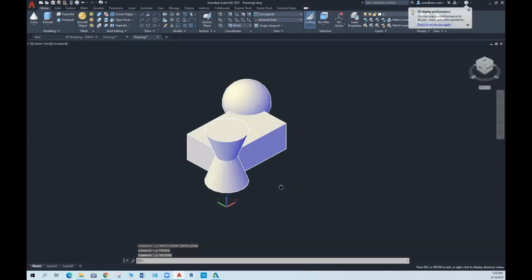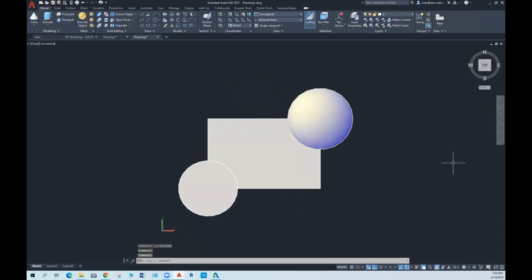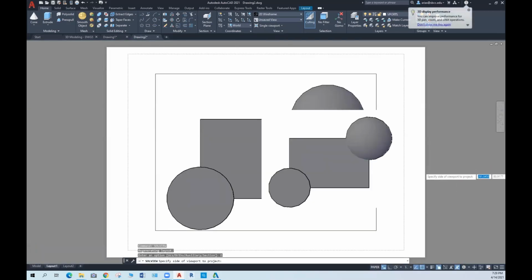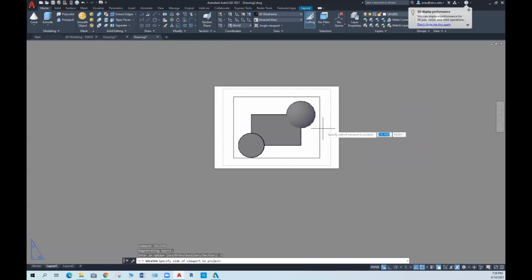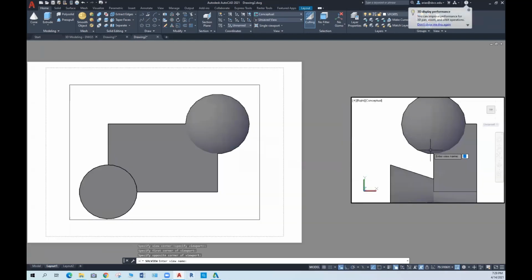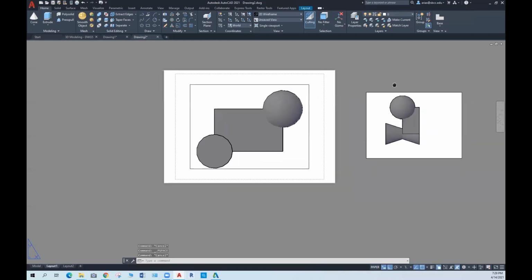And in here on model space, before I do anything, I'm going to go to top view. And now I am going to type Solve View again. And I'm going to create an orthographic projection. Again, from the right side, click where I want the center to be. Now enter, create the viewport. And now give it a name, right side view. Press enter, and then you can just escape and end the selection.